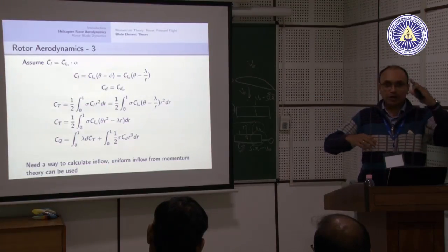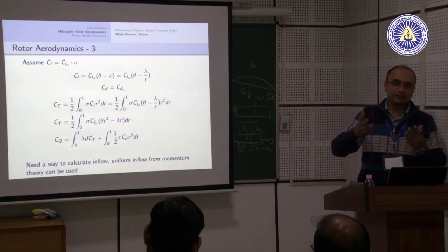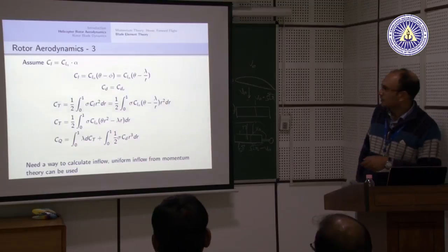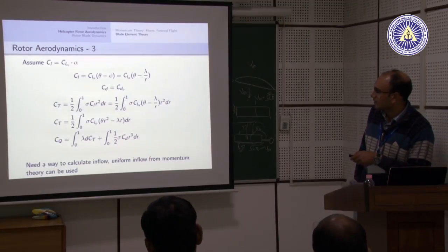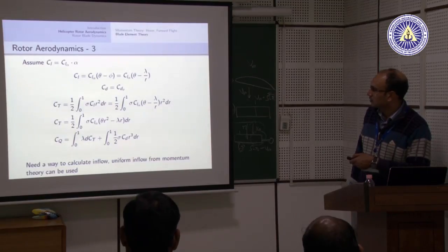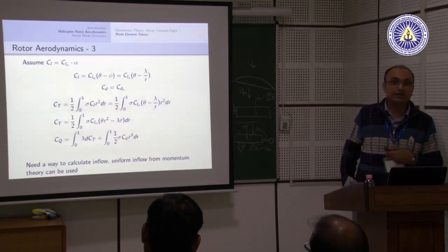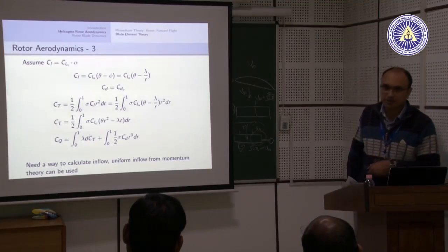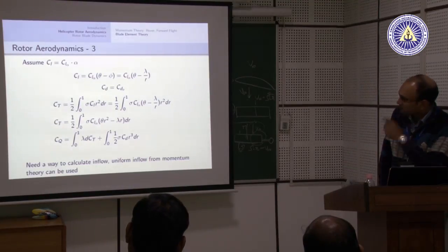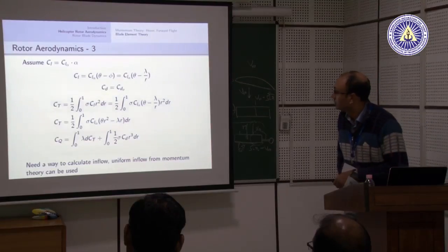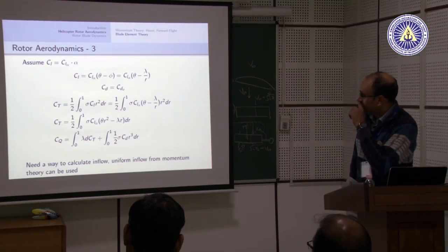So, beyond a particular angle of attack, the lift will not increase, but up to some point it is fairly linear, and if you are operating in that linear part, then I can approximate the lift generation by CL equal to CL alpha into alpha. Also, this is only valid for a symmetric airfoil. For a cambered airfoil, you will probably also have some beta here, plus beta or minus beta, but for simple calculation this is fairly good enough. It does not make such a big difference.